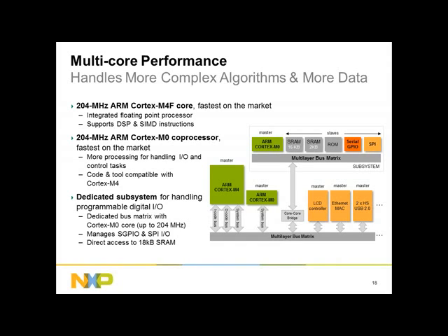Okay, so as long as that new submaster peripheral handler Cortex-M0 is executing from the memory there, it's zero wait state. If it has to go across the bus, you will pay a 6 to 10 cycle penalty. So if you need things on the other side of the bus to run fast, you might be using the other Cortex-M0.